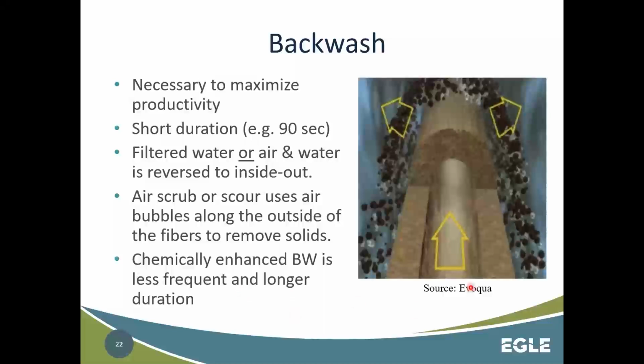And then, as I said, some of these systems are set up to do a chemically enhanced backwash. So they might do the same thing, but with a highly chlorinated water. And sometimes that is a longer duration where it might have a soak step in there just to help out.